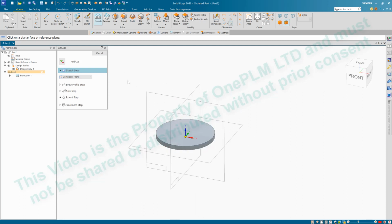Next, we're going to stay in the extrude command. Notice this stays live. We can press escape to cancel, or we can choose whatever we want. We don't have to get rid of this. But this time, we're going to click on the top face. This means that this feature will always build up on top of the existing feature.